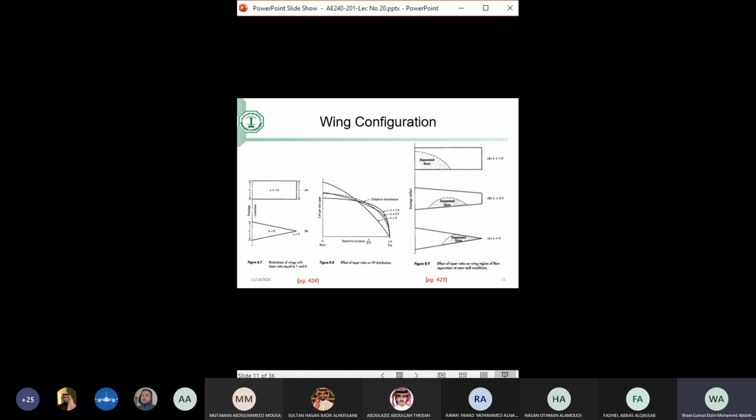So what do we make out of this? It turns out that most low subsonic aircraft will have a taper ratio of about 0.5. If you look at the Beechcraft aircraft that sometimes take off from the airbase in our backyard, you will see it has a tapered wing, and you can judge that this distance over that distance is about 1.5. Have a look at most of the tapered Cessna aircraft. Taper should be 0.5. Okay, so that's a sort of agreed upon value that we will use.